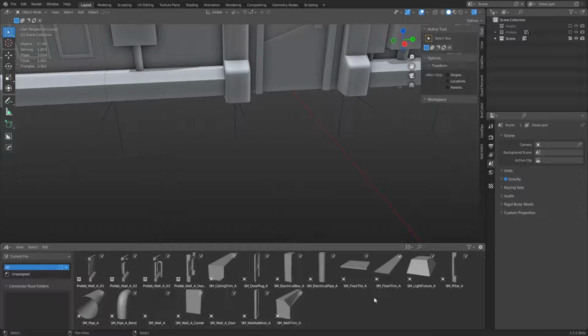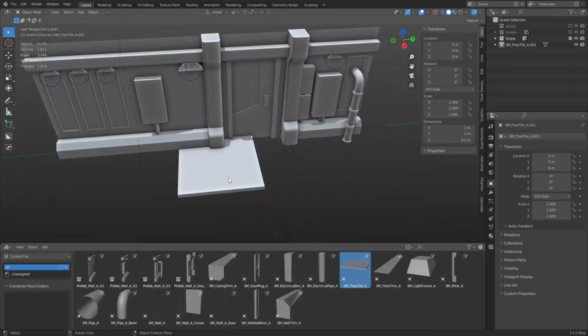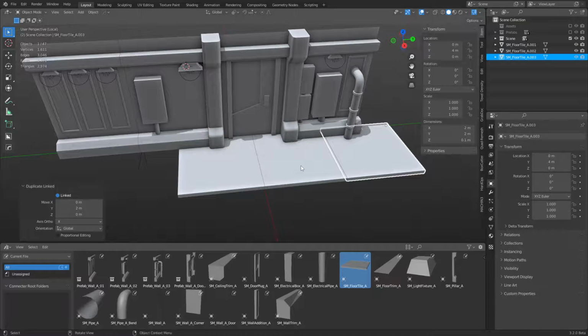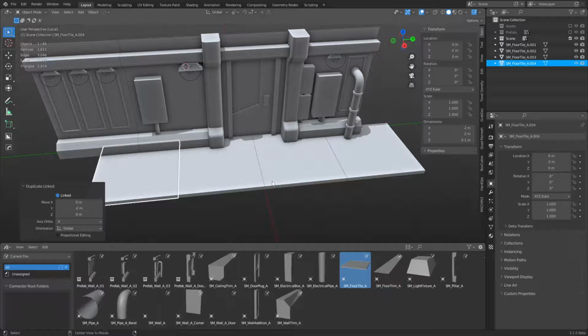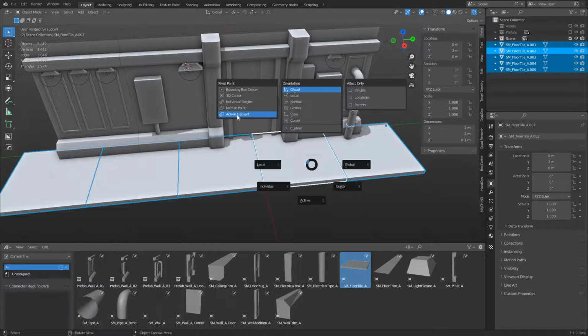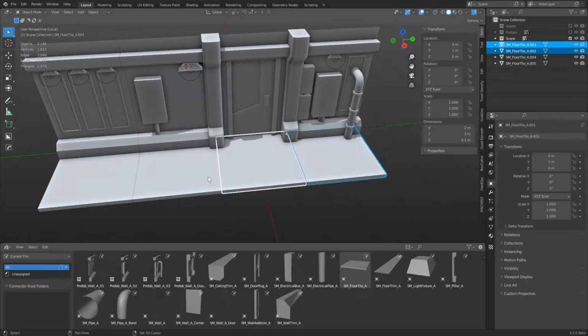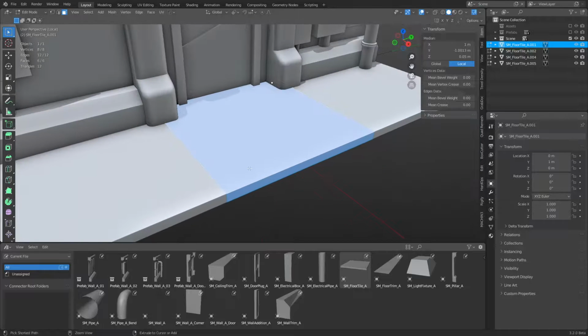So we have our asset though, and we can just drag and drop it out. Cool. Make sure it's instance, select, place it like so. Alt D. Make sure we have it all in instance. Let's just move these all together real quick, and we're going to do active element. So that we're doing a group, so we gotta do that. We don't need one of those. All right, so because this is not a prefab, you could create your floors as prefabs as well.